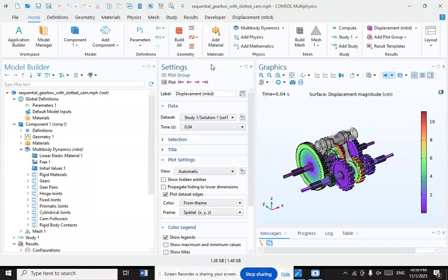These devices automatically match the speed of the input shaft with that of the gear being selected, thus removing the need for the driver to use techniques such as double clutching. The synchromesh transmission was invented in 1919 by Earl Avery Thompson and first used on production cars by Cadillac in 1928. The need for synchromesh in a constant mesh transmission is that the dog clutch requires the input shaft speed to match that of the gear being selected. Otherwise, the dog teeth will fail to engage and a loud grinding sound will be heard as they clatter together.